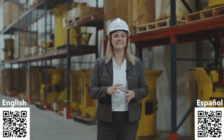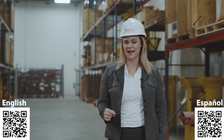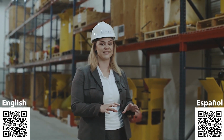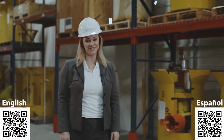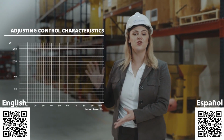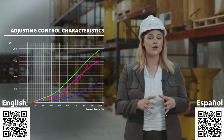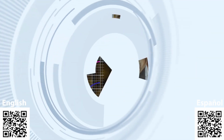The trim cage is compression loaded and constructed as a solid element of tungsten carbide for durability and ease of service. Custom port designs are available to optimize performance depending on the fluid type and gas-oil ratio. This chart demonstrates a few possible flow control curves. However, MasterFlow can provide almost any control characteristic to fit the needs.